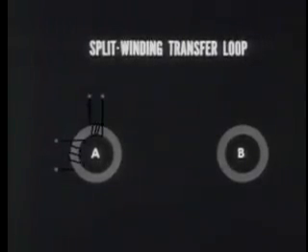We'll add 2 input windings first. The input on the left is connected so that the current flows into it on the non-dot side only. This is the one that our logical diagram showed as coming in at time t0 and setting core A to binary 1. At the top, current comes in on the dot side, setting core A to binary 0, and the